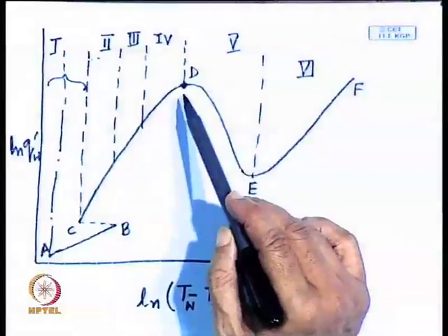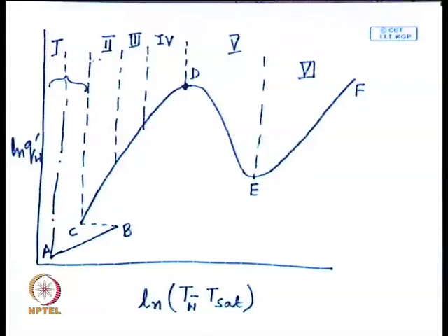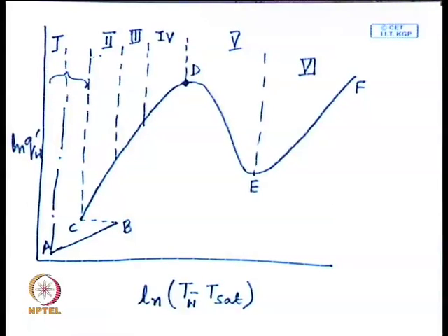Okay. So, here we will find a very interesting phenomenon, and it is also important from the safety of the heater, that here wall temperature is increasing, but heat flux is decreasing. So, in general wall temperature is increasing, heat transfer coefficient is decreasing. So, this is a very reverse trend. Generally, when we increase the surface temperature or we increase the temperature difference, we get an increase or enhancement in the heat flux, but here the reverse is operating. Here the reverse is seen in this particular boiling phenomenon.